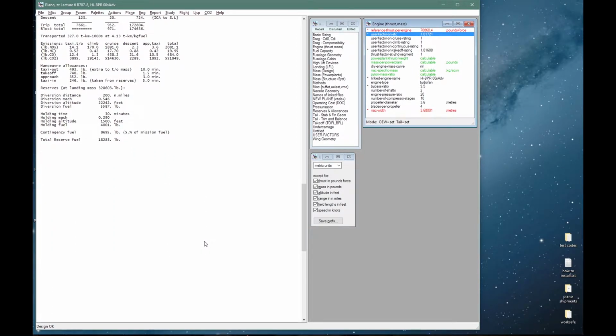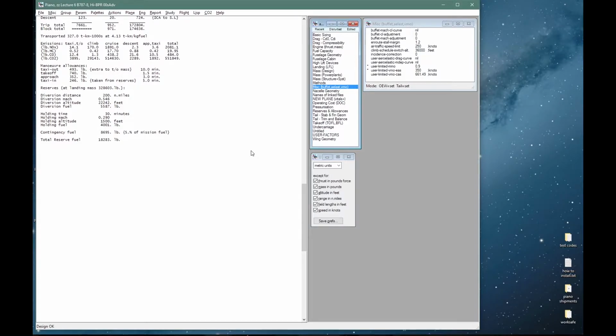In between weights and aerodynamics, let's now consider aeroelasticity. Without detailed prior knowledge, our rationale is going to be that we can reasonably expect the combined trailing edge variable camber and load alleviation systems and their associated software to use conservative early settings in order to reduce structural loads at the highest weights, at least until enough operational experience has been gained. There are some indications of early drag levels that hint at as much as a 5% potential penalty at the highest weights.